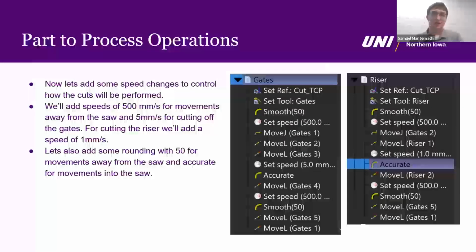So this is where we have to start working in some of the information we know about each of our cutting operations. In this case, we're using a pretty underpowered bandsaw, so we're going to have to move very slowly through each of these cuts. In our operation, it's a multi-purpose bandsaw where it's used for operations beyond just the robot. So it's not sized quite the same as you would have for some foundry operations, especially for the thicker gates and risers.